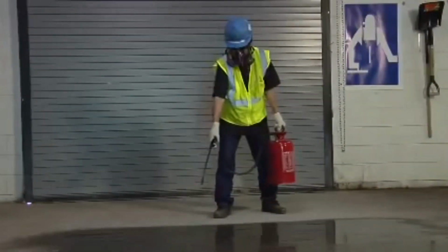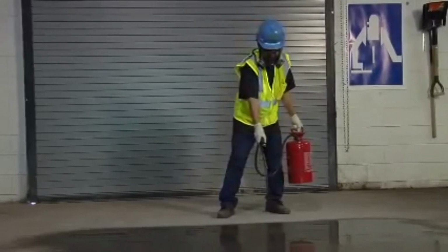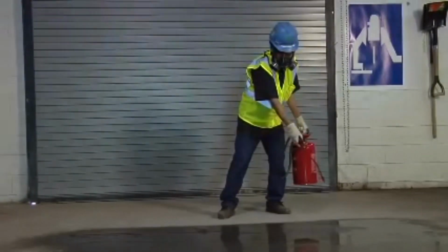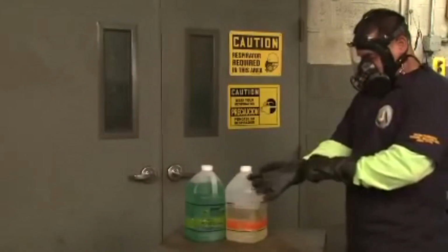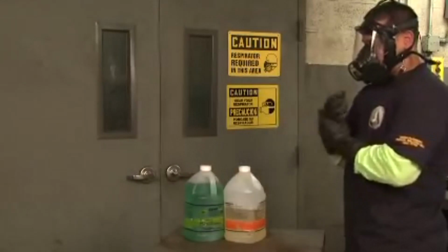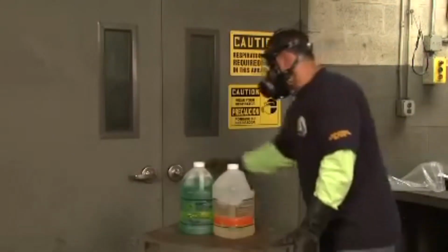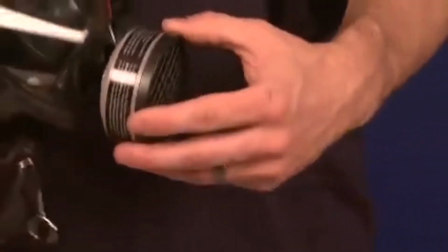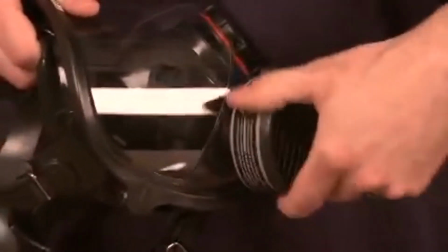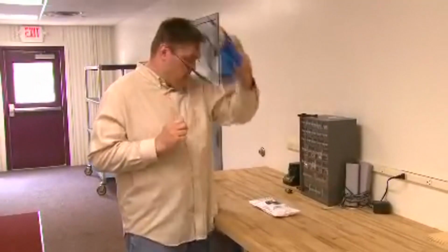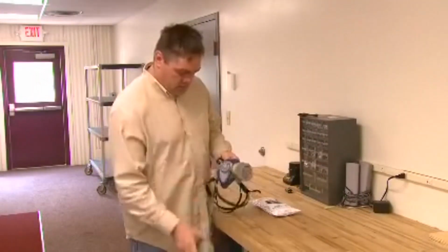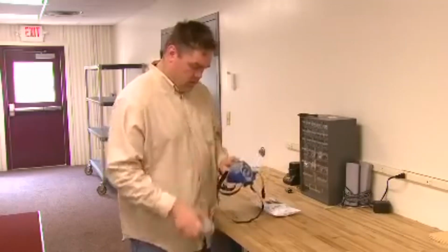Some gas and vapor hazards require the use of respirator cartridges or canisters containing materials that absorb or remove these hazards from the air. However, cartridges or canisters can only absorb a limited amount of hazardous gas or vapor. To ensure your protection, they must be replaced before they reach this limit. If you use a respirator for protection against gases and vapors, your employer must determine a schedule for replacing worn-out cartridges or canisters. This is known as a change-out schedule.